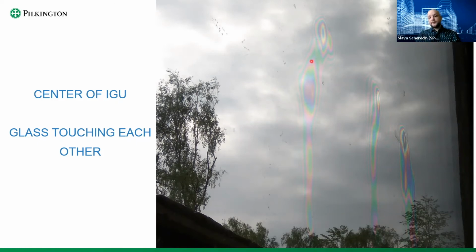See here, rainbow spots. That means that in these places, the two glass panes are either touching each other, or they're less than 1 millimeter from one another. So almost touching. And that is a very bad thing, because that means that the glass design, the IG unit design, glass thickness, and spacer width, some of them have been chosen incorrectly.